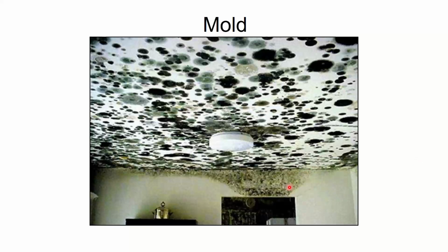If you have things like this, where I have mold here and I don't have mold there, that probably means the water is coming from behind the wall somewhere. Right? In this case, maybe it's a roof leak. If you had mold on all of these walls in its entirety, covering kind of an even pattern, that probably means it's getting the moisture from the air. Why do we care where it's coming from? Well, 1, we can't get rid of the moisture if we don't know the source. And 2, if the moisture is coming from the air, it's an HVAC problem.